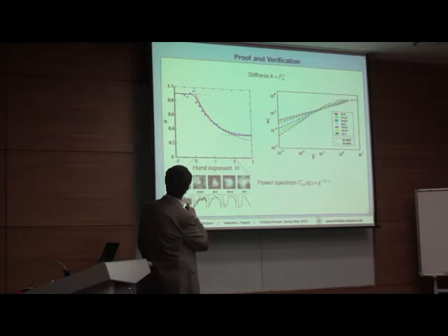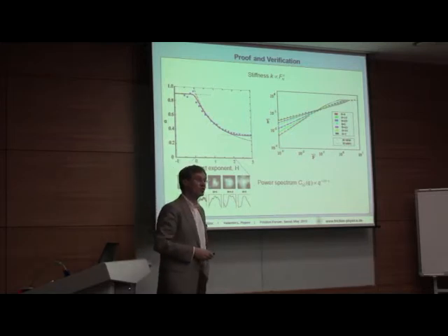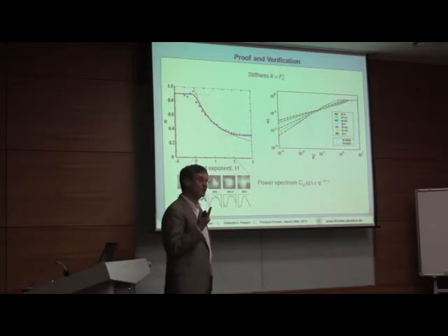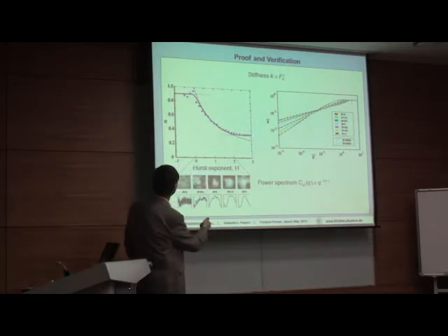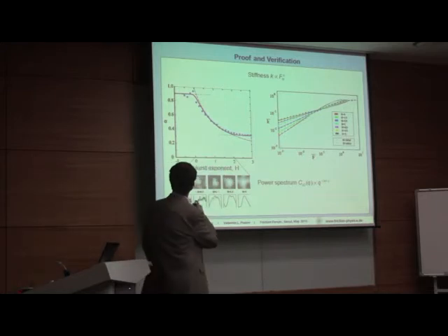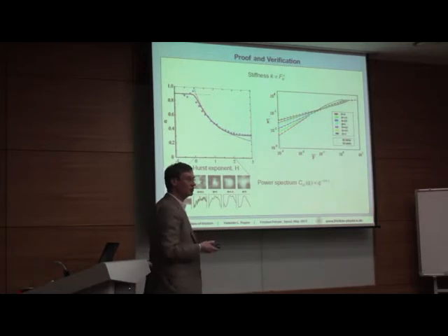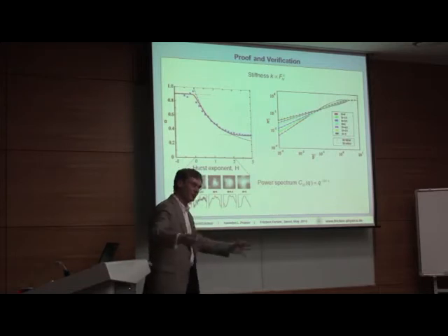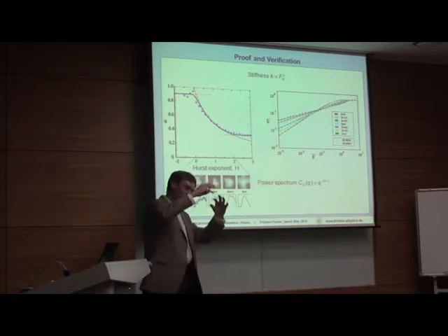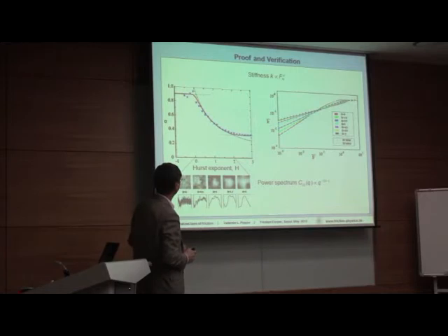Then there is some part here, and then there is some part here. Here you have just one smooth asperity with this Hertzian contact, and alpha is 1/3. This is the result for Hertzian contact. Here is something like Greenwood and Williamson. It is completely independent, large, high and independent asperities, and this is true fractal: larger and then smaller and then smaller and so on.